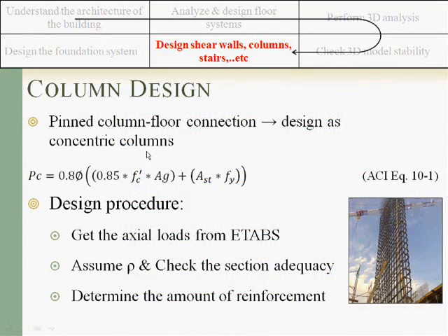Now we reach the column design. We have designed the columns as pinned columns, and this assumption is very conservative because you are taking all the loads to the shear walls. We have had a lot of discussion about this, and we will do a separate presentation clarifying the problem of the rigid connection of the beam or floor to the column versus the simple connection, and why we can or cannot use a pin column connection in concrete structures. This will be displayed in a separate presentation.